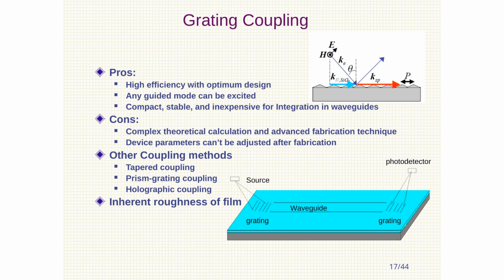Grating coupling offers high efficiency and can excite any guided mode, making it ideal for compact, stable, and cost-effective waveguide integration. However, it requires complex calculations and advanced fabrication with fixed device parameters post-fabrication. Alternative methods include tapered, prism grating, and holographic coupling, each with unique advantages and challenges.